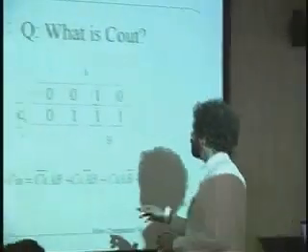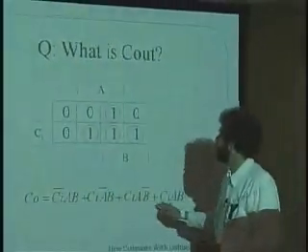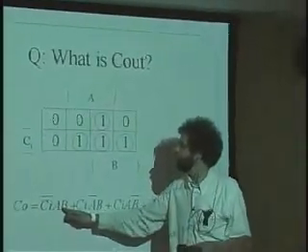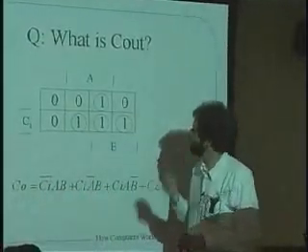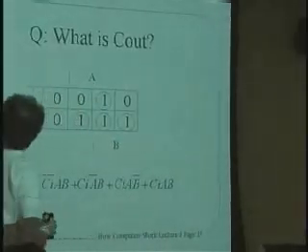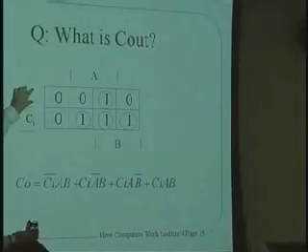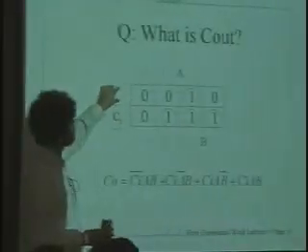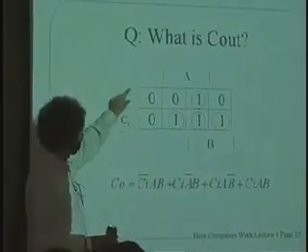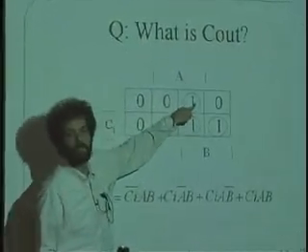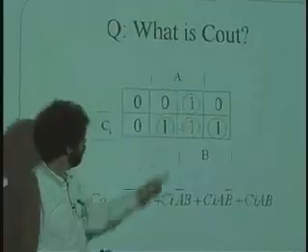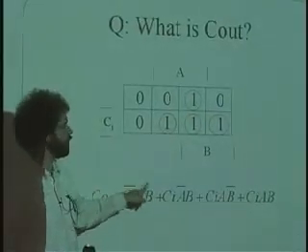So now let's look at a two-dimensional K-map with three input terms and understand the product terms. Here we have four product terms. Each of them has three inputs that it is sensitive to. C sub I bar A, B. Now where is C sub I bar A, B on this thing? C sub I is not true. That's up here. Okay, here's the place where C sub I is true. Here's the place where C sub I is not true. So C sub I bar, A should be true and B should be true. So we come along here. That one.